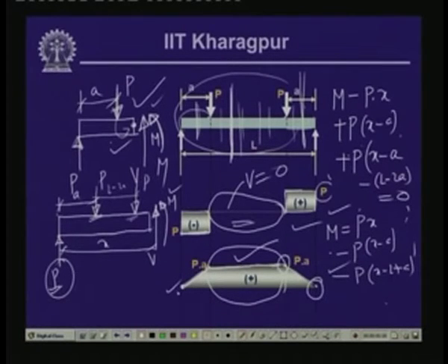And again, if you take the slope, here you see that (Pa minus 0) by a is P, and negative of P is the shear force here. And again here, (0 minus Pa) by a, so minus P, so minus of minus P equals plus P, which is the shear at this particular point. So again it satisfies the criteria as we have seen earlier.